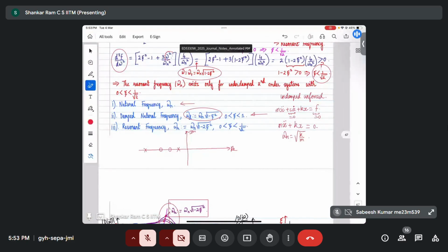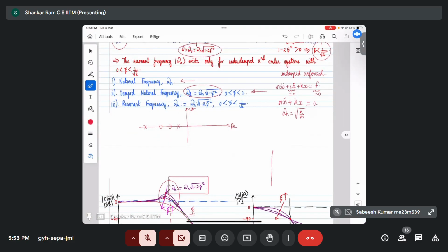Once again, let's say I am only taking two zeros. What did we learn in root locus? We learned that if there is an open loop zero, each branch of the root locus must end at an open loop zero, right? Essentially, the root locus will start from a pole and go to a zero.